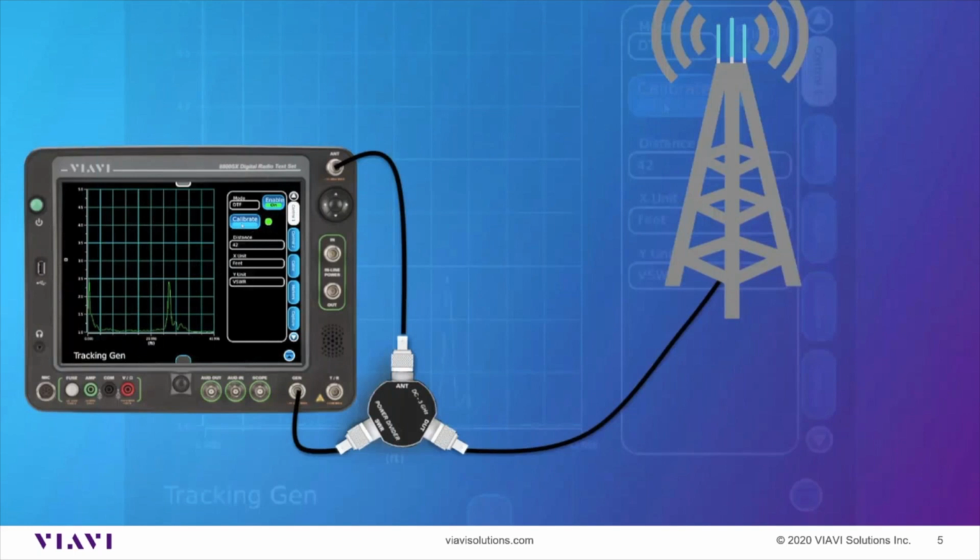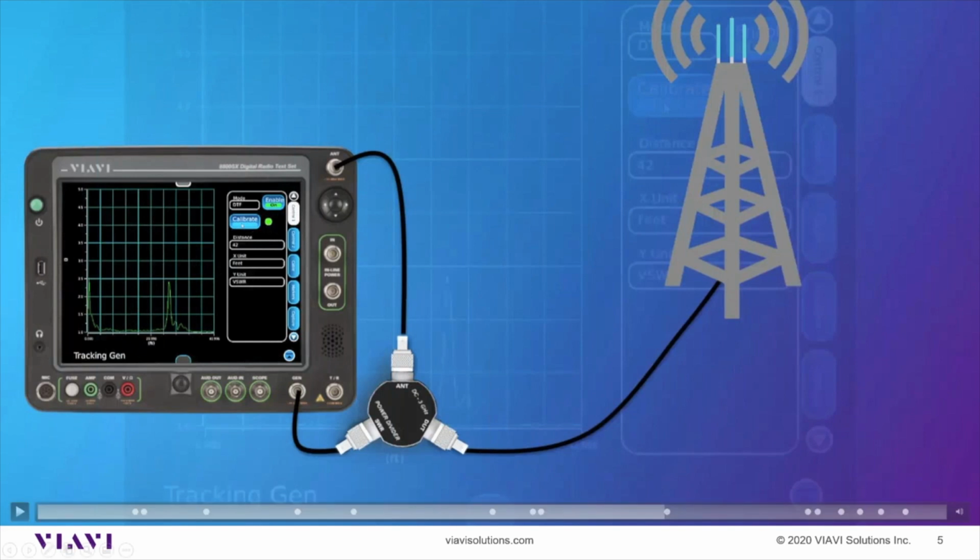That's your estimated length. And then you would be able to tell where that fault's at. Is it down at the base station, halfway up the tower, that sort of thing. So this is a real useful tool, especially after you found out that you've got bad VSWR. So let's let it run here a little bit.